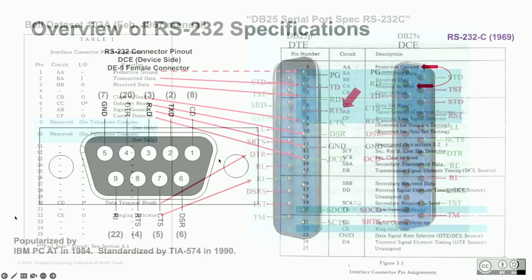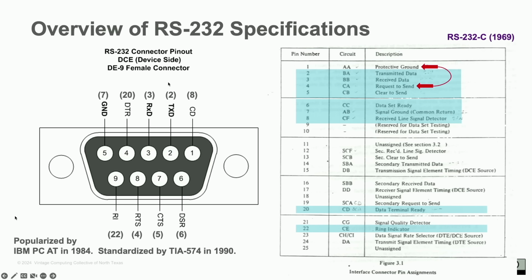Okay. Next. So yeah, most of us play with the smaller version of the RS-232, only the 9-pin version. We don't really need, that confuses us with a parallel cable. This calls out the secondary transmissions. There was like a sub-channel where you could potentially get a little more efficient transmission using those, and 2 pins were unassigned. So kind of dealer's choice on what you use those pins for. So that's RS-232 established as a standard in 1969.